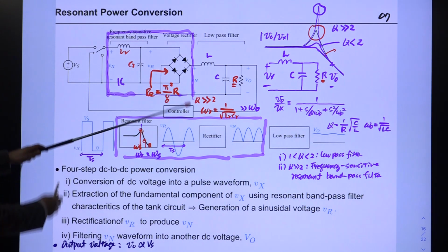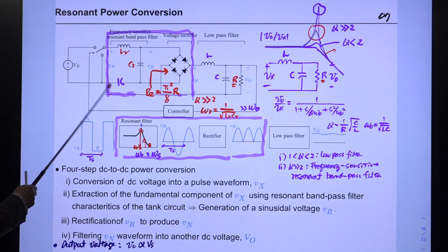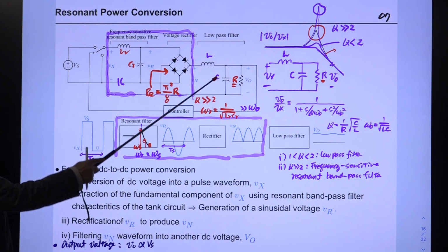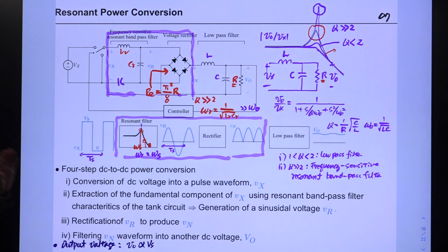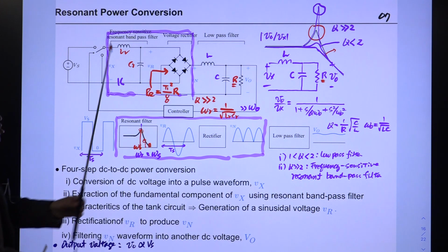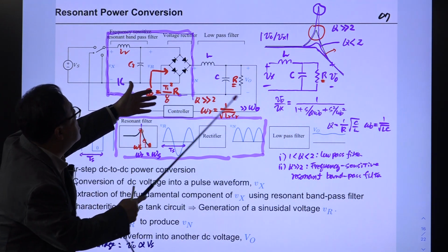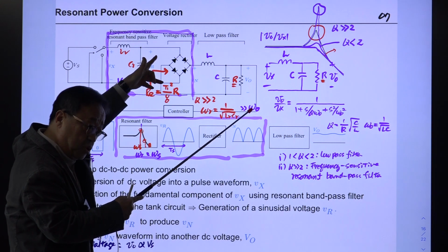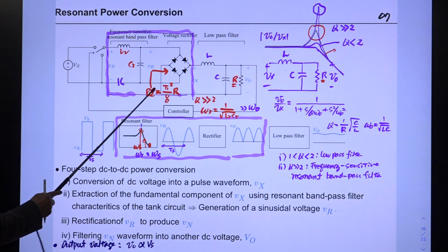In this part, we have this structure. This is a low pass filter structure. This part remains the same as the PWM converter, but we have this additional part. In this structure, we have two low pass filters. The structure of this is a low pass filter, and the structure of this is L, C, we don't have R. We don't have a resistor, but functionally, we'll see this. I'll explain this later in detail. This part, seen from this port, can be approximated as a single resistor.